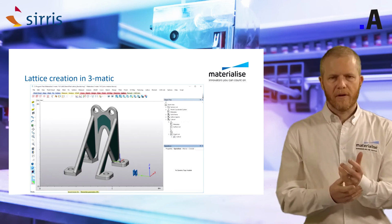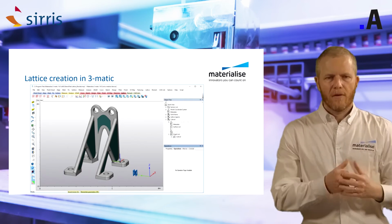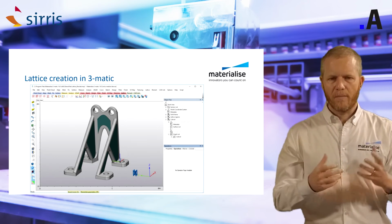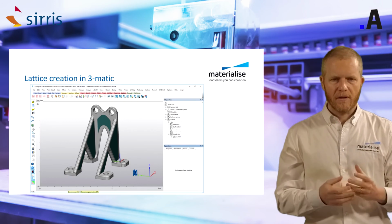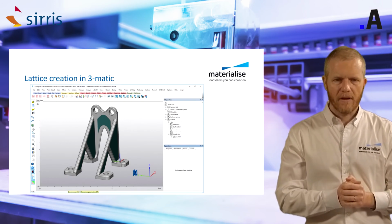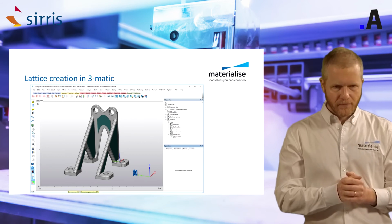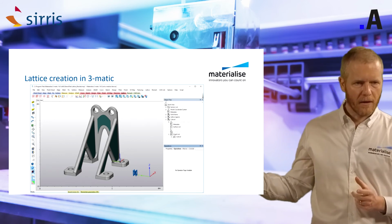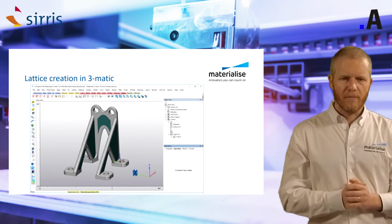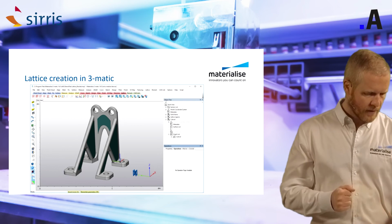So how does it work in the software? You specify the volumes that you want to replace with the lattice structures. In this case, those are the volumes in green in the part, and in blue at the bottom you see the unit cell that will be used to generate the lattice structure.